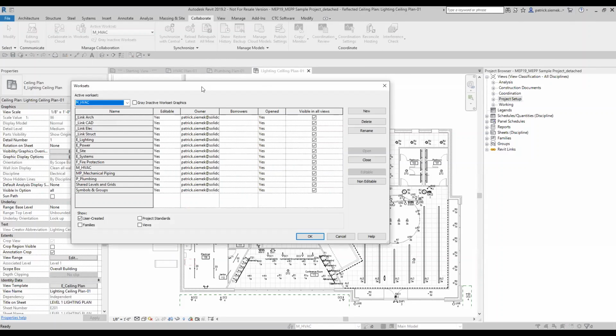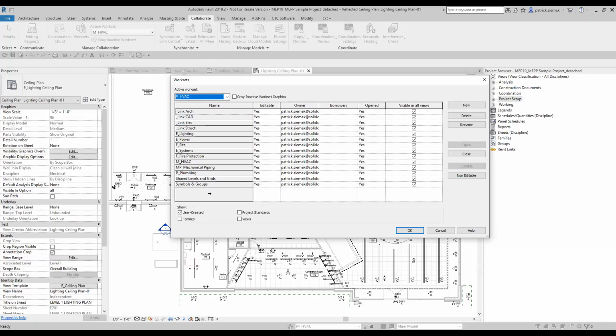you can start to see they already have been initialized specifically for links and also for different system types. Once I start going in depth more into the working areas, you can start to see by identifying and using the work sets, specific view templates drive graphically how things will show. Again, for the option of having things to easily turn on and off during the creation of the project, but also identifying if we are in the correct areas and you are modeling in the correct spaces. This is also a great indicator, utilizing your view templates, which have work sets already driven based off of those.